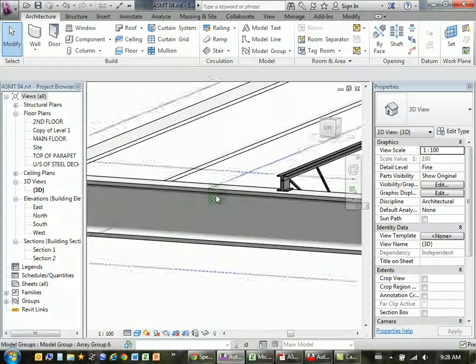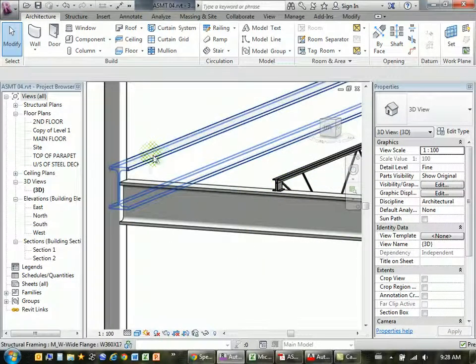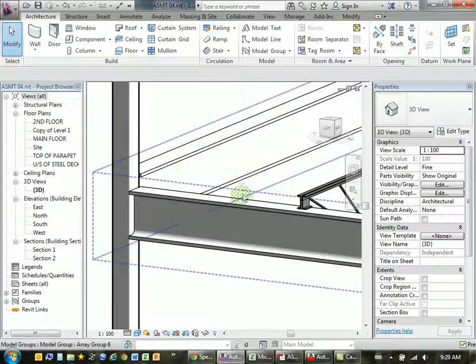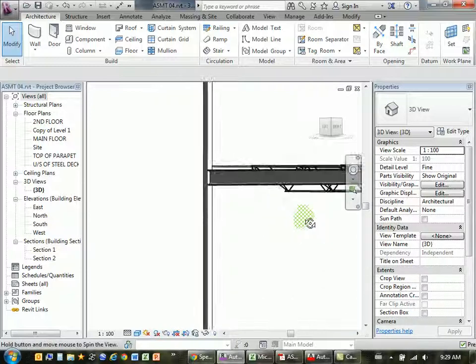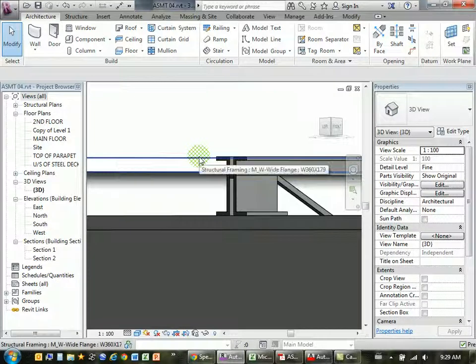If those beams were at the same height, then when I put the joists on the north-south beams, the tops of the joists would be higher than the beams on the perimeter, and then that decking, that floor, wouldn't run straight across. So that's why I have to have that subtly different set of circumstances there. It just means that everything lines up. You can see in that view there, I've got tops of joists and tops of beams lining up. 100 millimeters. Yeah.